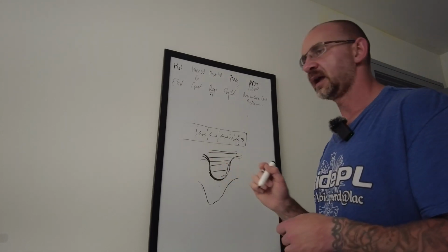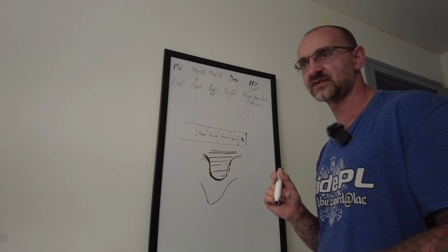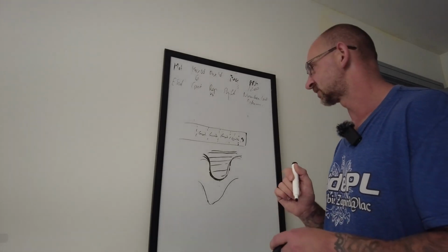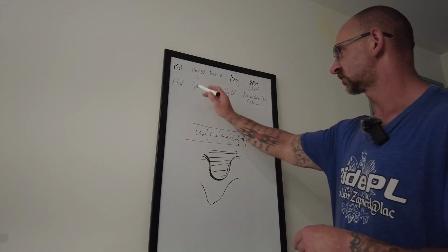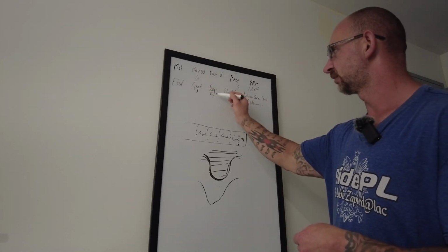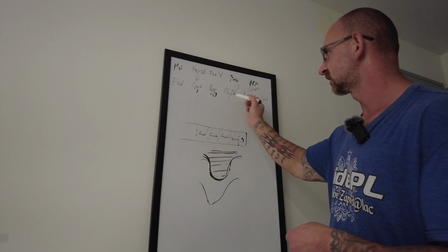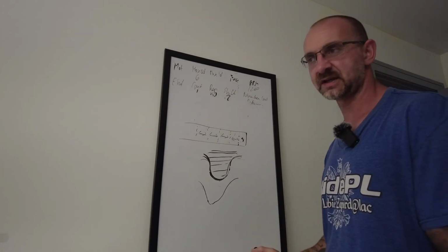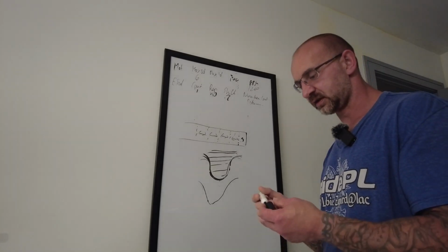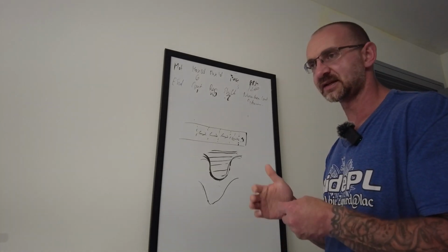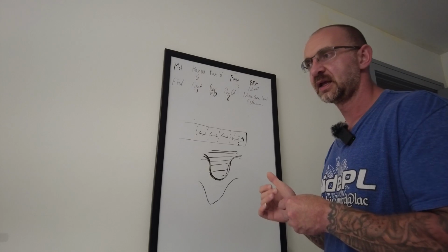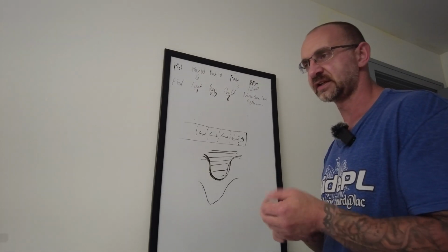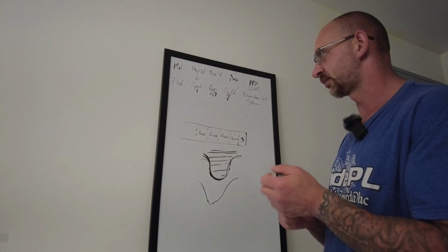For example, I've got 50 grooves like that, spaced apart 0.200, so I can tell the machine to repeat. If I have 50 grooves spaced every 0.200, I shift 0.200 each time. This feature is very useful. I use it a lot on a lot of things, and it keeps the machining fairly simple.